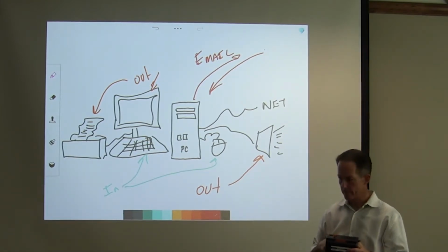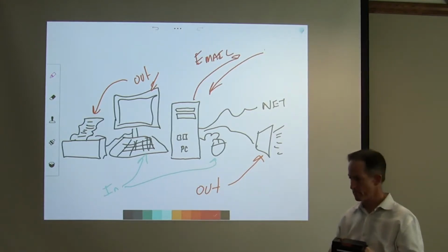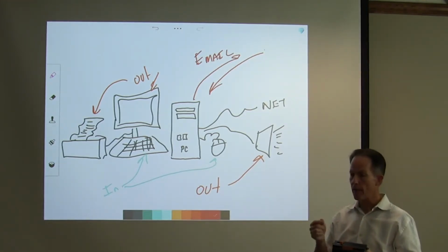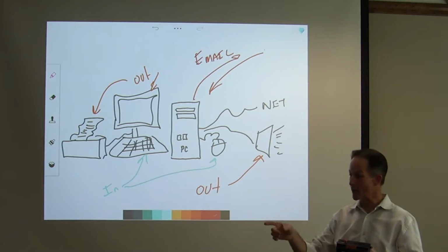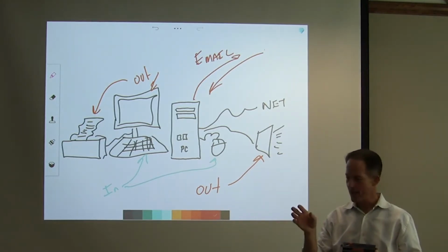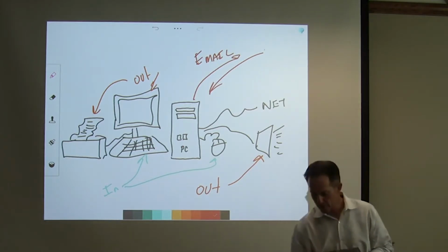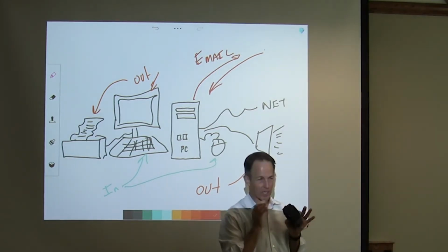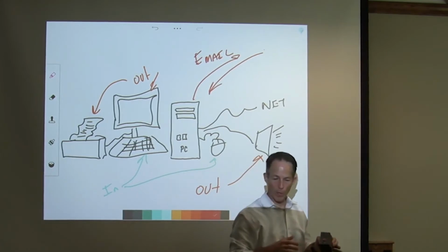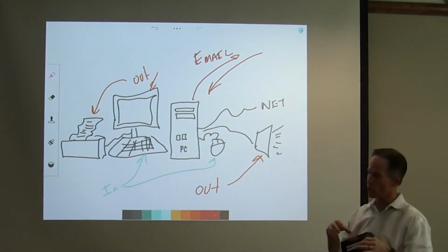So the only place that's an output is the sensor itself. Everything else is an input to the card. Yes, and that's where it gets tricky, right? Because if I'm standing at the sensor, it's an output from the sensor, but we always look at things as if we're the controller.